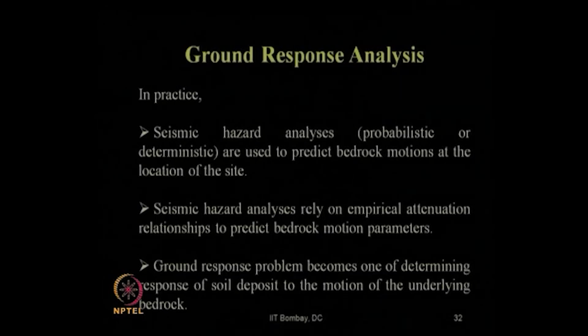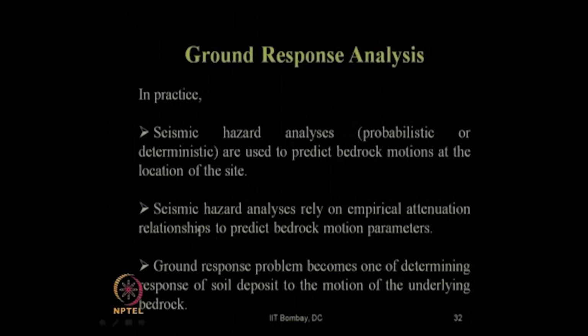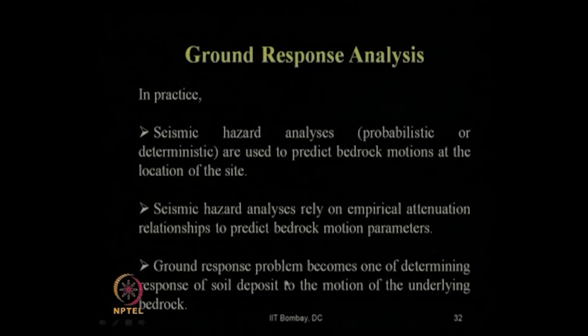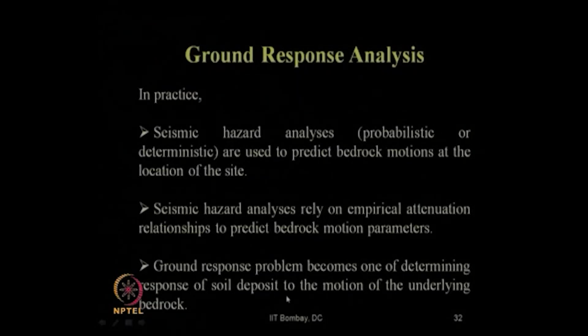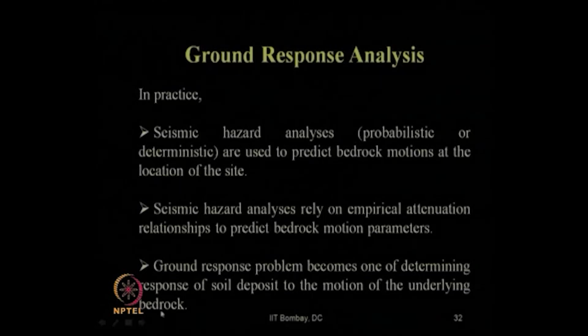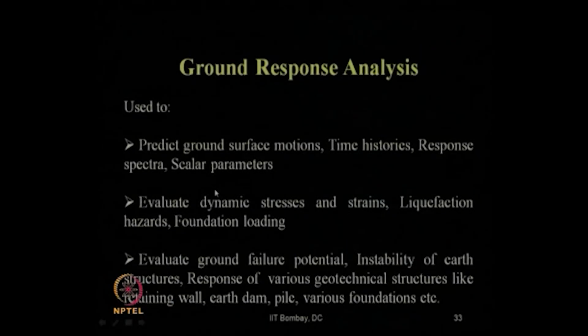If you change your data set, you will probably arrive at another attenuation relationship. So, to predict the bedrock motion parameters, you have to rely on these, and the ground response problem becomes one of determining the response of the soil deposit to the motion of the underlying bedrock. That is what we adopt when we start any design process at a particular site.